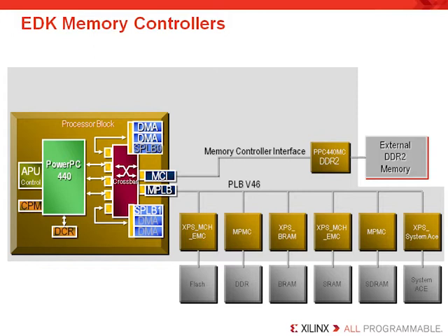The next is another external memory controller or EMC, and that's attached to an off-chip SRAM, unlike the earlier one which was connected to an off-chip flash device. The next component is another multi-port memory controller or MPMC connected to, this time, an off-chip SDRAM, again showing you that this is a programmable device that can interface to different external memories.